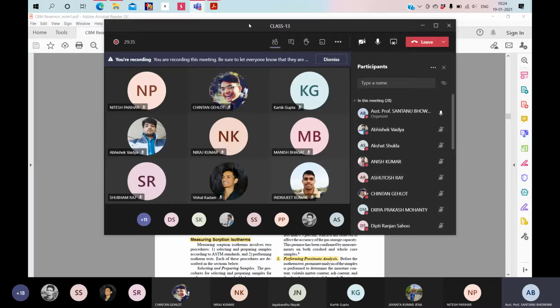You have to take the sample just coming after the blasting, from the freshly exposed roof, and wrap it up with bubble wrap. Why? Because when the coal is in situ, it is pressurized and has no contact with the atmosphere, so whatever gases and pore pressure are inside the coal remain intact.